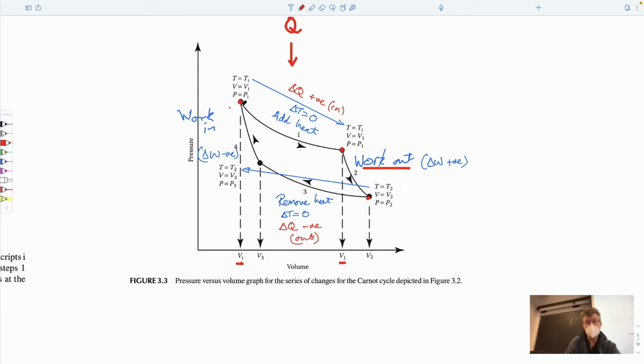So maybe you start off taking it out of the reservoir at 200 C. You'd like to be able to cool it down to, say, 20 degrees centigrade, ambient air temperature. Probably you can't get there, and that affects your efficiency. And so you condense it to get to here, get it to be a liquid, compress it again fully to being a liquid, and then the cycle keeps on going.